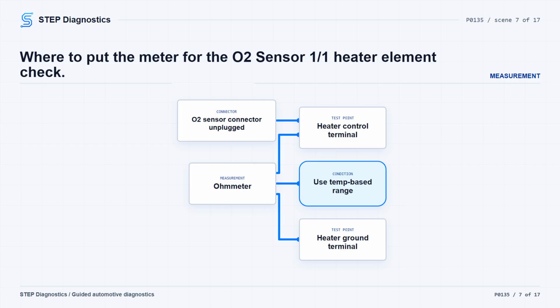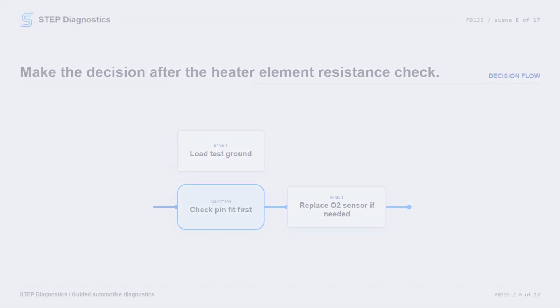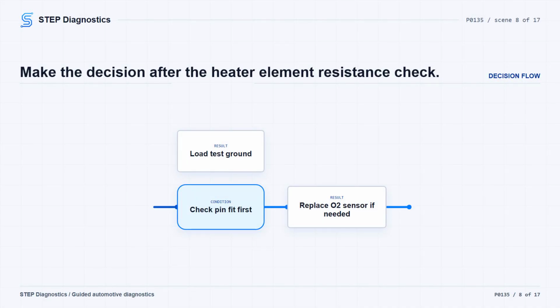The acceptable range shown is 0 degrees C, 32 degrees F, 1.4 ohms; 20 degrees C, 68 degrees F, 3.4 ohms; and 100 degrees C, 212 degrees F, 85.5 ohms. The maximum allowable resistance would be 12.5 ohms at 1000 degrees C.